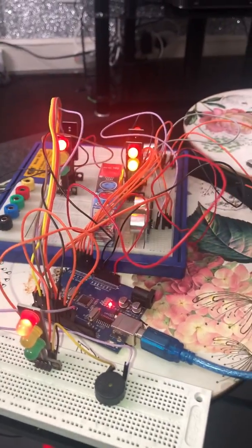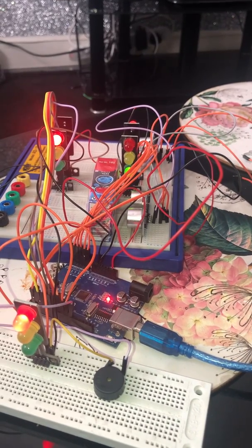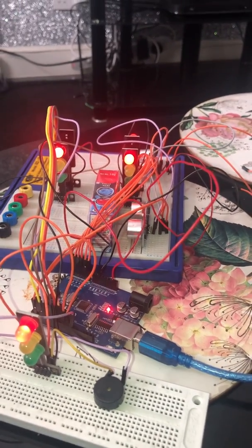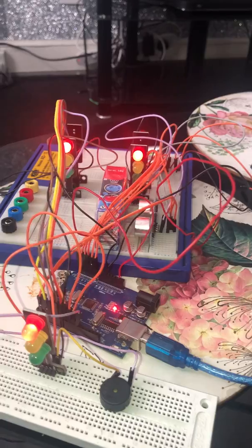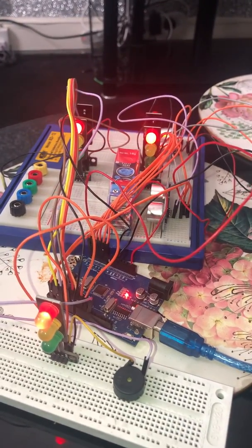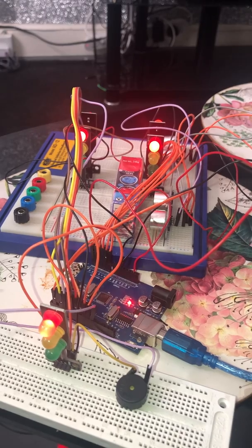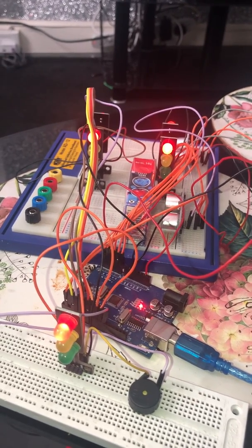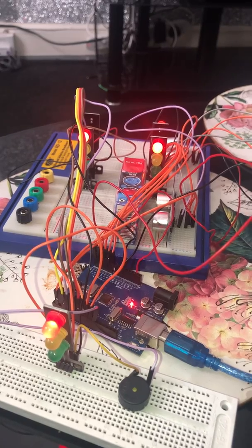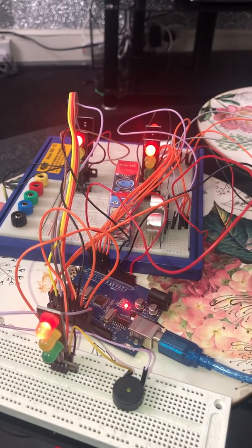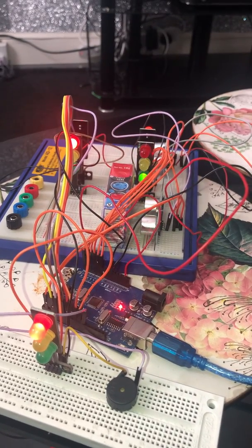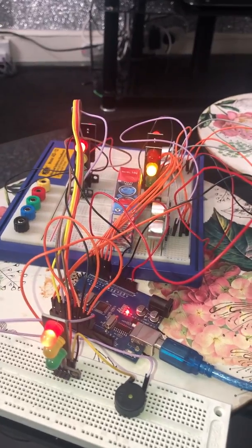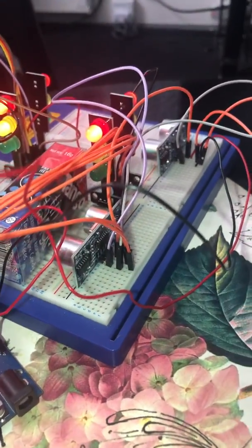As you can see, on the Arduino UNO, if we go to the official website, we will see that the Arduino UNO only has 2 pins that are able to interrupt. Those pins are pin number 2 and 3. So we have a limitation that we cannot use more pins for interruption, because only 2 pins are available. That's why I only use this sensor instead of using that one.